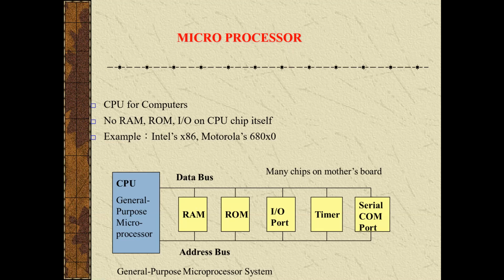Here, as I have mentioned in the figure, the microprocessor itself is a general purpose unit. It can address memory to operate. It consists of ALU, accumulator, working register, program counter, stack pointer, clock, interrupt circuit, etc. But in a microcontroller, all these things are built in together with the devices that are external in a microprocessor system.